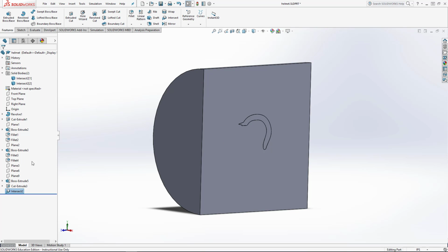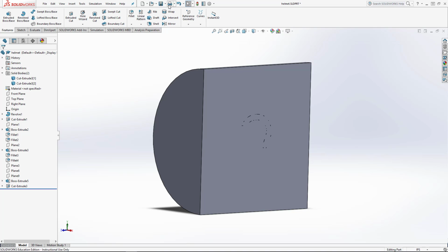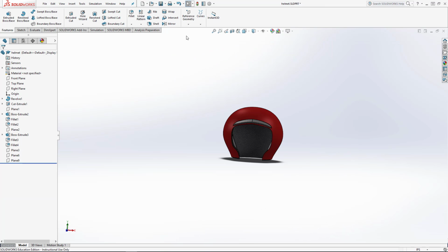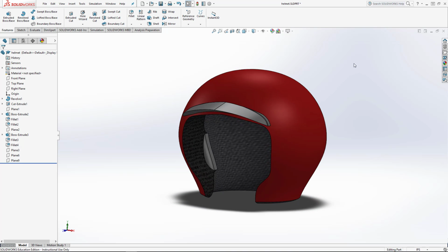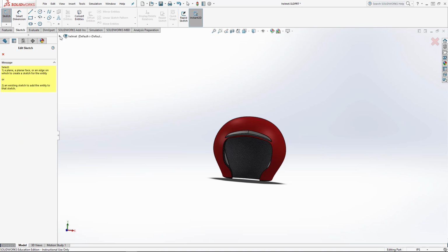All right, the second option, if we go back and we're going to delete these, go back to our original, what we had. Actually, probably should undo here. Let me undo everything I did here. All right, so back to just the basic helmet. The other option is to do the filling of the domain, defining where the fluid domain is, and let that be done in ANSYS. All right, and the way we do that is we start out actually very similar in the same way, and we're going to draw that circle around the helmet, but instead of it being a solid cylinder, it's going to be a pipe.